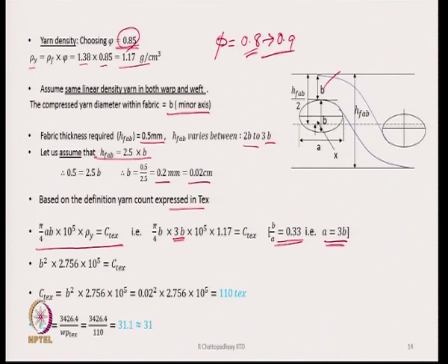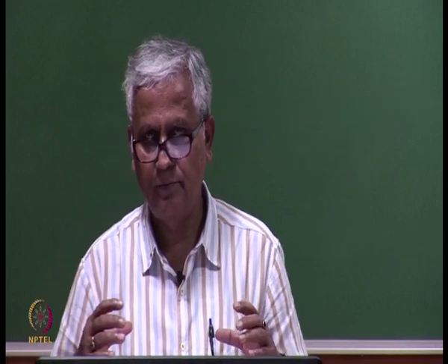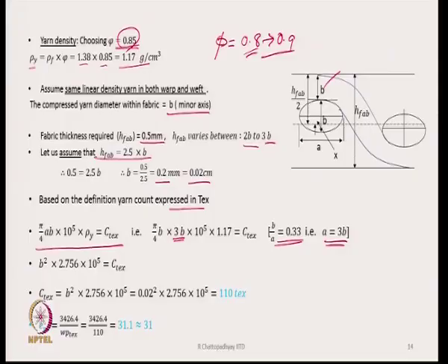If we look back at the ellipticity values, then we will see that when the yarn twist is 0 or the lowest, when it is going to deform maximum, this is the value we usually get, and therefore, A has been replaced by 3B in this case, because we are going to form a liner from filament yarn which are hardly twisted or have very low twist. So, maximum deformation is going to take place.